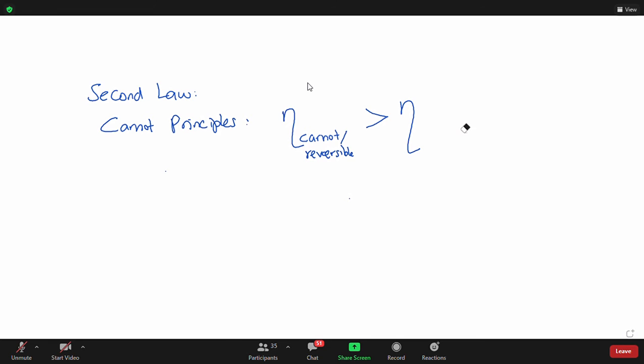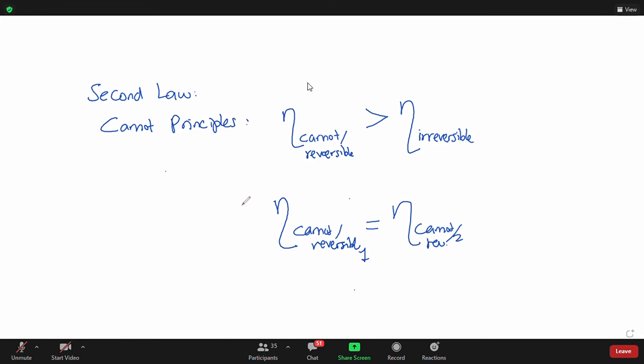Always, always. A reversible cycle will always have a higher efficiency. The other thing it says is if it is a Carnot reversible cycle, it will have the same efficiency as another reversible cycle if they are operating between the same two temperature reservoirs, TH and TL.